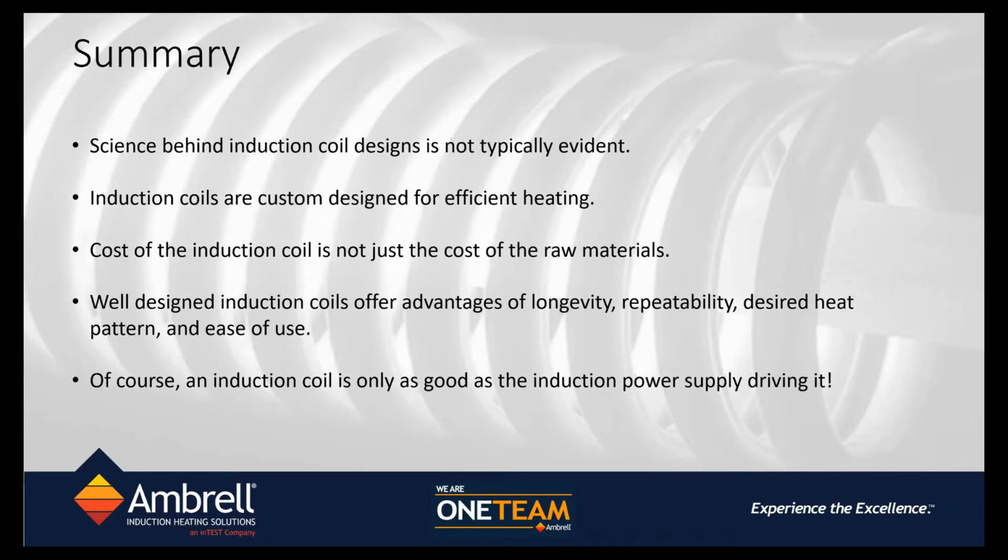Very good question. So without knowing all the details as to how big the parts are and what is the typical problem that is being faced, ceramics obviously are not very robust for that kind of thermal shock, because you may have flux in the area, you may be having handling issues in the area, so ceramics may not work.